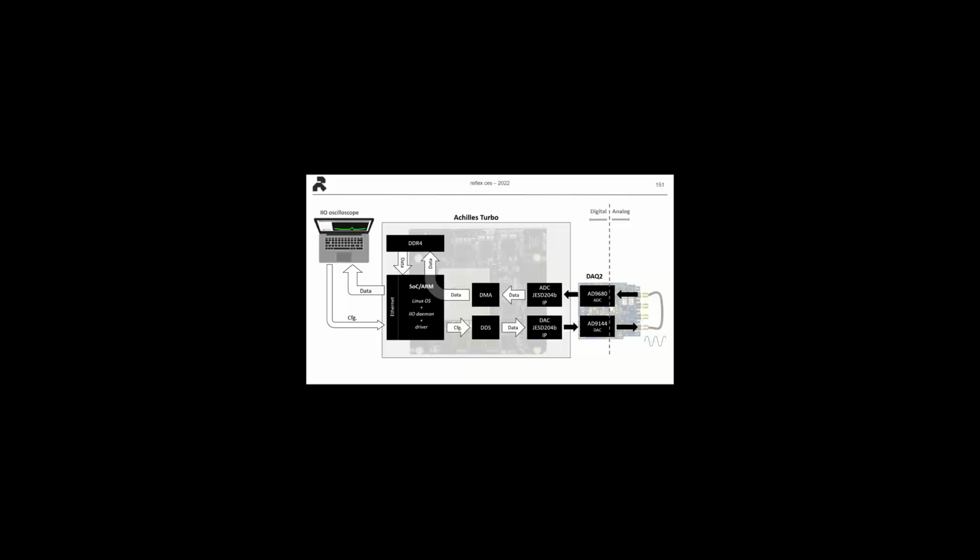And that will also set up the data that we are looking at here. So going from the HPS, the processor side of the module, you have the configuration. That's where the Linux OS is running on the HPS side. So we have the driver, we configure the JESD, and that's where we send the data to the DAC, do the loopback.